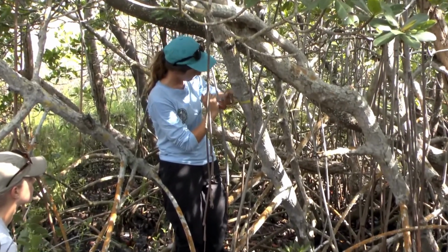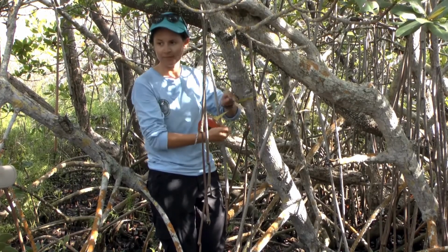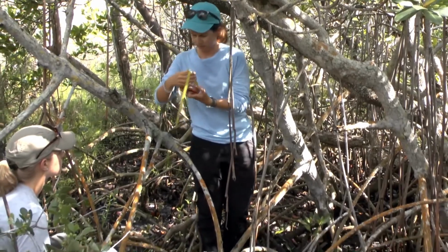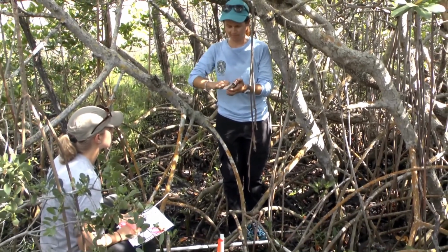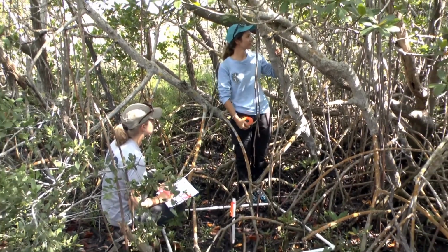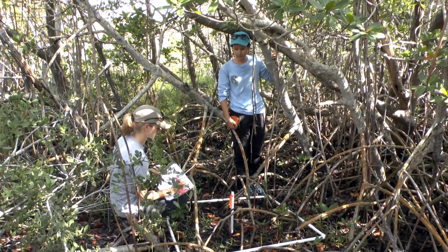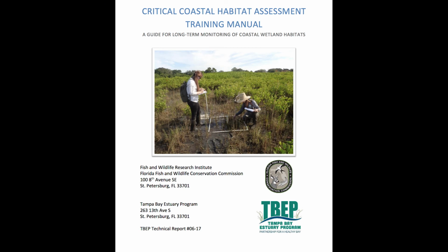Tree diameter may be measured using tree calipers or a diameter tape, while tree height may be measured using a surveying rod or clinometer. PCQ sampling may be omitted if you would need to sample beyond the current vegetative zone in order to locate a tree of sufficient height. For instance, PCQ sampling is not needed in salt marsh zones that lack tall trees. See references in the accompanying manual for instructions on how to calculate forest characteristics from PCQ data.